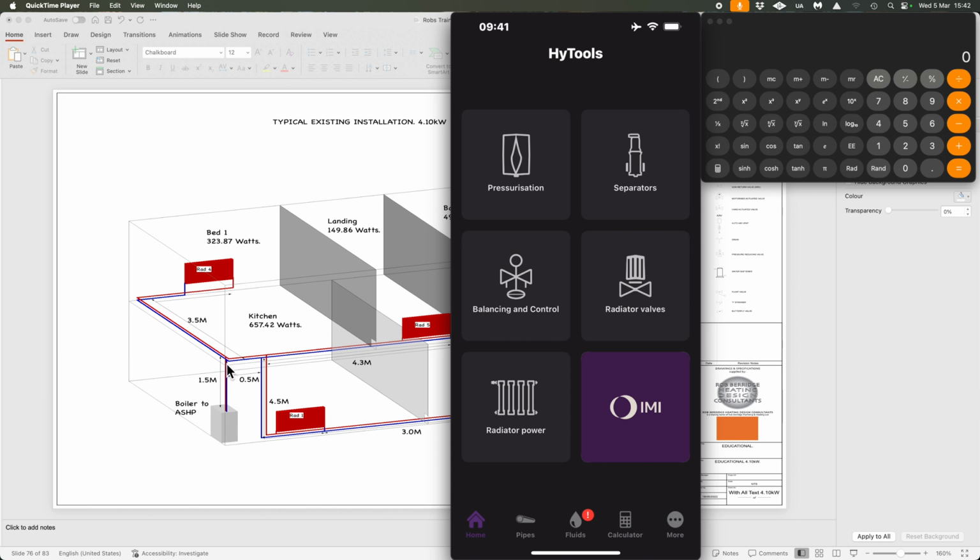You'll generally see there's 22 millimeter installed or 28 millimeter installed, and it'll run down, or 22 will run all the way down. Then we might be 15 mil drops there, or something along those lines. But I'm going to throw some curveballs in, and we'll add them up as we go. So let's go on to our calculator, and we know what our total heat loss is.